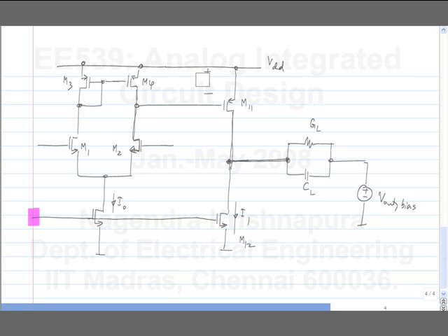Actually, even before that, which is the plus and which is the minus terminal of the op amp? Before we had this to be plus and this to be minus, and this was the output. Now from here to here there is an inversion because it's a common source amplifier. And this is the output. So I bias this at some VCM plus VD by 2, then VCM minus VD by 2. What is the DC gain of the circuit?